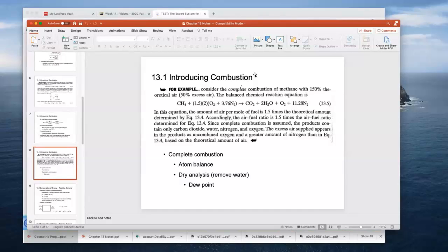That is referred to as the combustion heat of the individual fuel. Typically, the combustion heat is written for a stoichiometric component. So one would take out the 1.5 and just have the 2 times these. You would not have this term here, the oxygen, and you would have a smaller amount of nitrogen.